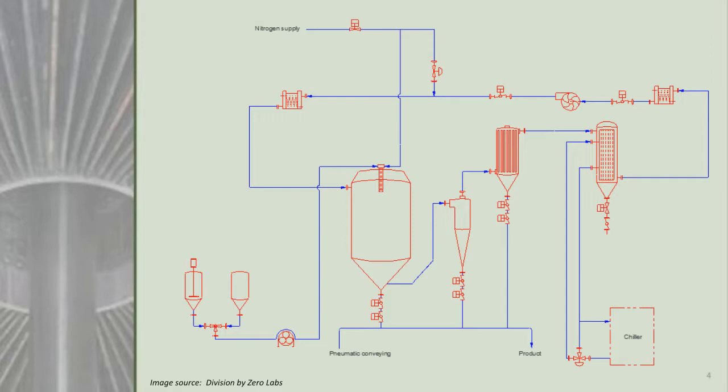And then everything else is basically the same, except that we also now have a solvent. As we're exiting the baghouse, this solvent needs to be recovered so that we can reuse the gas, since the gas is now saturated with solvent. So we put a condenser in line, and this will cool the gas and collect solvent underneath. Since we've cooled it, we now need to preheat it before we can use it again. So there's a second heater, a preheater, on the inlet side of the blower, and on the exhaust side of the blower, there's a second heater that brings it back up to the drying temperature.